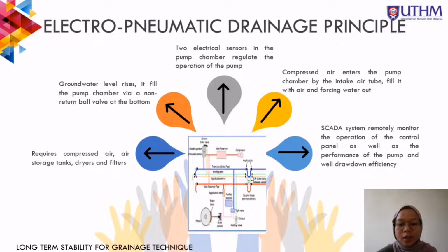The compressed air supply is controlled by the solenoid switch, which allows it to move from the air compressor and its air tank to the compressed air input tube and then the pump. An air dryer and filter dry the air before it enters the solenoid. A water level sensor in the pump is connected to an electrical cable that runs through the duct to the control panel.